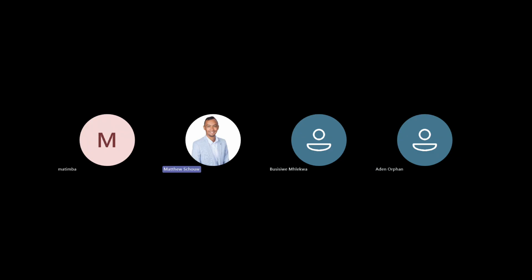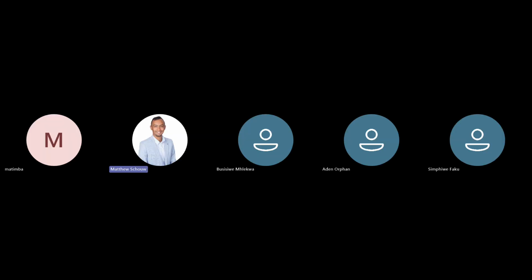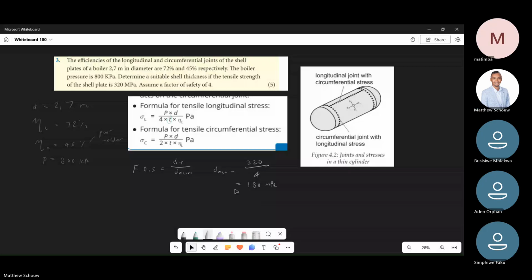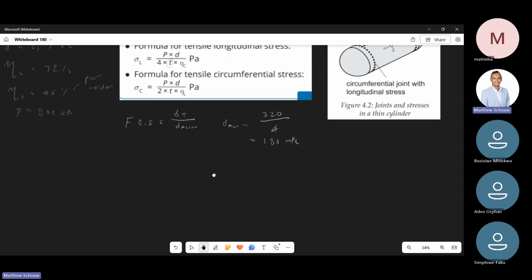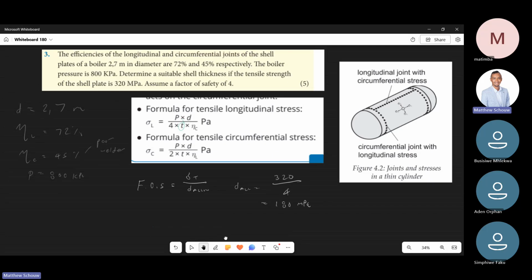So it's nothing crazy. It's a simple equation, used in design all over. So in that case, we know our plate can handle 320 megapascals, but we say, oh no, depending on the application, it's a boiler, only 180 megapascals. So now I'm going to do the first part and I want you to do the next part. Then we're going to work on this formula.